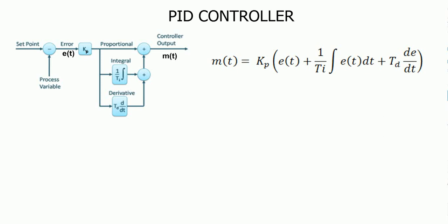There is an intuitive understanding of the PID as follows. The proportional part is the reaction part. The action here depends on the current value of the error. It deals with the present. As long as the error is not 0 at the present, this action is on. It has the effect of reacting quickly to reduce the time response, but it can overreact. That is, it can become too sensitive and lead to instability.